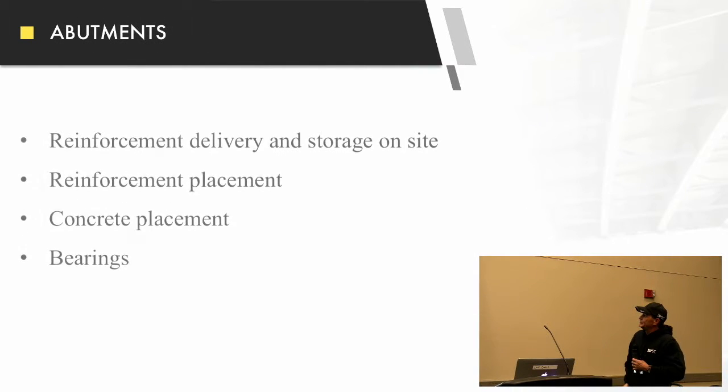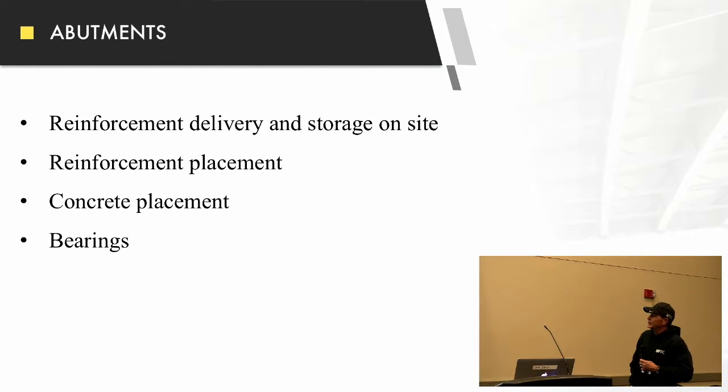On the abutments, reinforcing delivery and storage, that's a big one that I see a lot of times get overlooked. They'll bring out the flatbed and just start dropping rebar in the dirt, mud, throwing stuff on top of it.